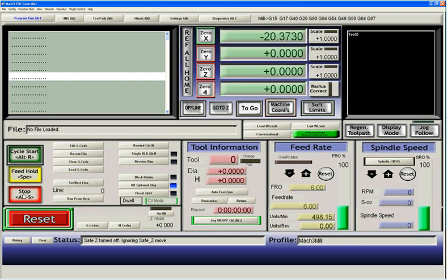But, and I'm going to stop this here so that you can see it. Let's 0 this again. You can see we're at a machine coordinate of +61, and we're going to home the system. The X begins its traverse backwards towards the switch, hits the switch, moves off, and zeros. But what zeros is the machine coordinate, not the normal coordinate. This is a G54 coordinate, which is in effect. We can now hit 0, and we are zeroed with a machine coordinate of -1, meaning true 0 is 1 off of the switch.